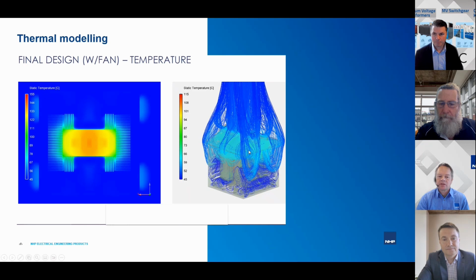Yes, you can see from the colouring of the transformer, we got an improvement in the temperature. But what we found is really it wasn't worth adding the fans. We had probably 4K difference in temperature, and we have a whole lot more chaotic flow going on. What we ended up finding is that once we'd refined the venting system, we had really, really good natural ventilation, and that's always the preferred way to go, is just rely on natural ventilation without using fans.